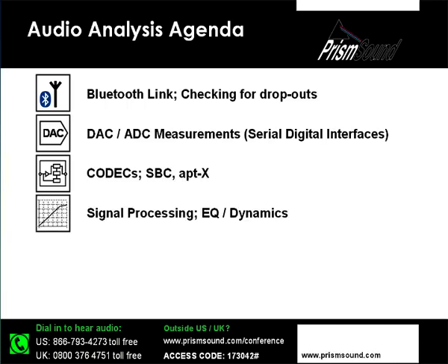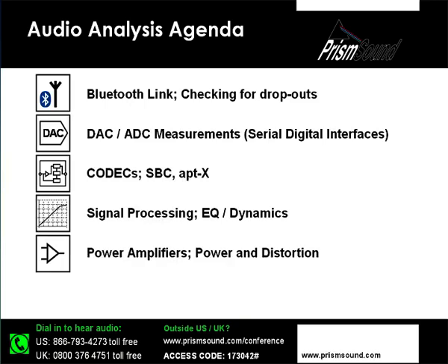You may well have some kind of signal processing, whether it's some basic band limiting in terms of equalization, or perhaps more sophisticated equalization to equalize out any resonances in the loudspeaker. There may be dynamics processing as well, perhaps to protect some of your components, the amplifiers, the transducers from being overdriven, etc. So we'll look at some measurements there.